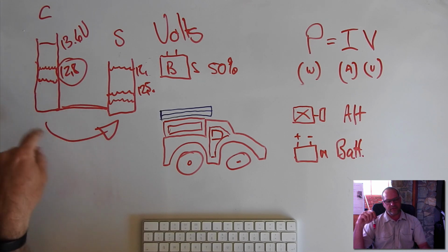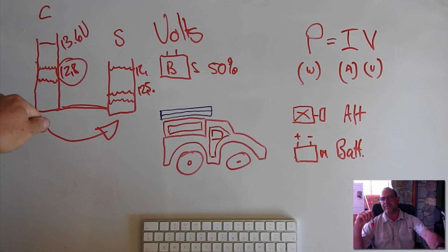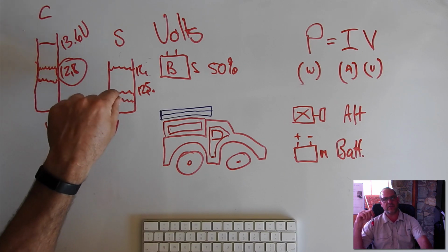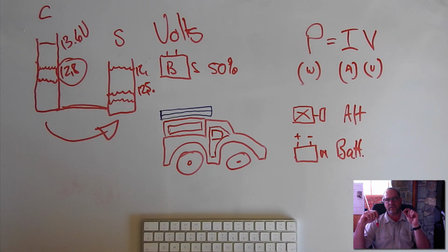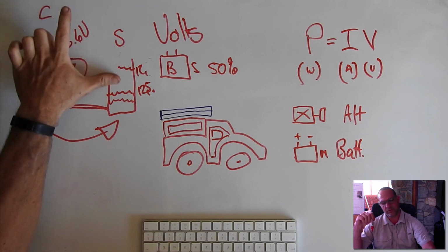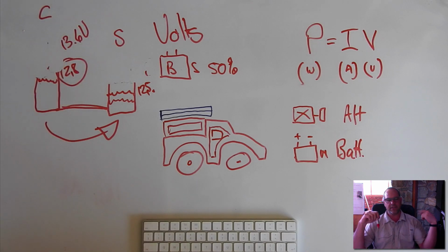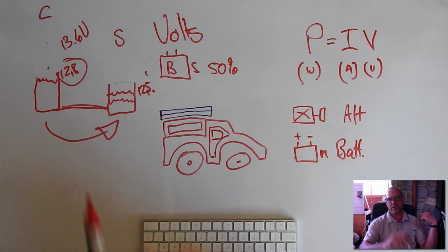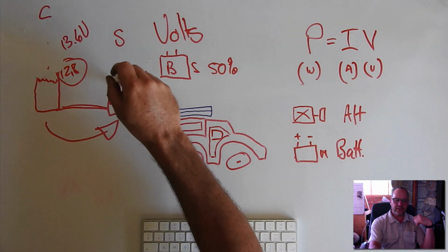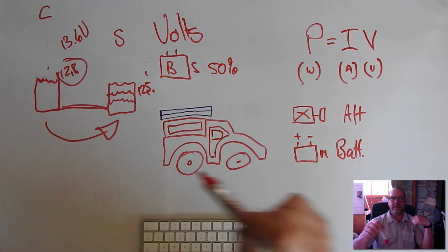The alternator is replacing the car battery power, but very slowly. But the car battery is sending power to the secondary so quickly that after 20 minutes of driving, the car battery has dropped in voltage down to the level of the secondary battery. We stopped to take a picture of a crocodile in one of the rivers, and the vehicle wouldn't start because the secondary battery had drained the main battery.